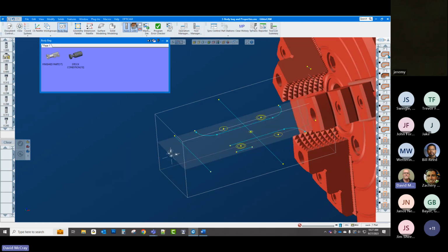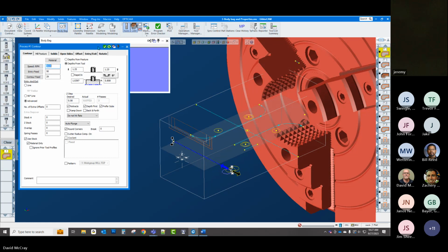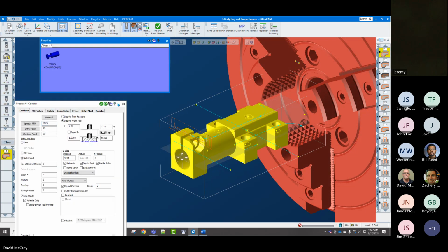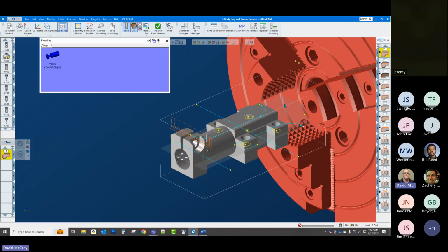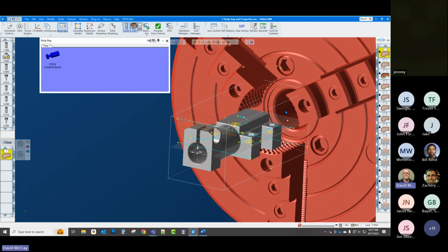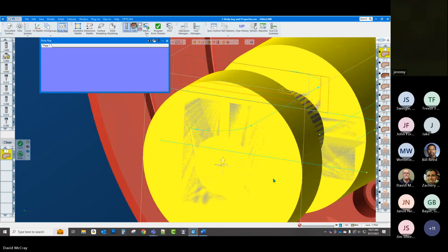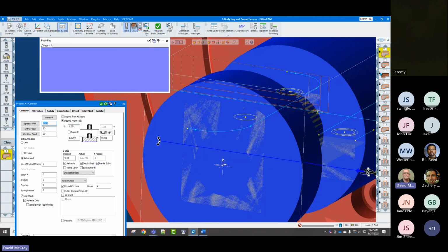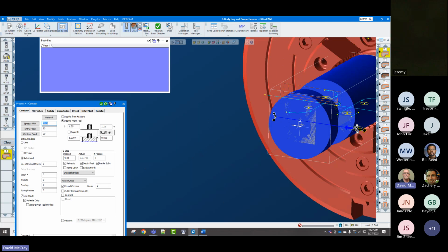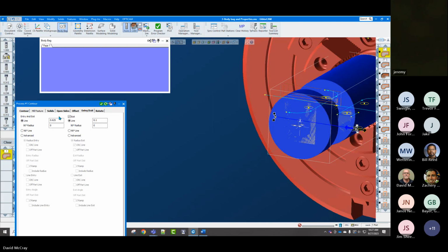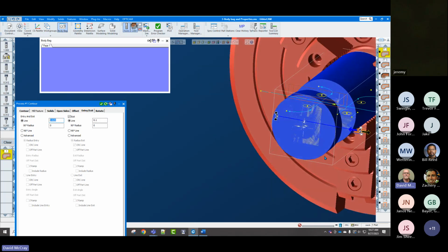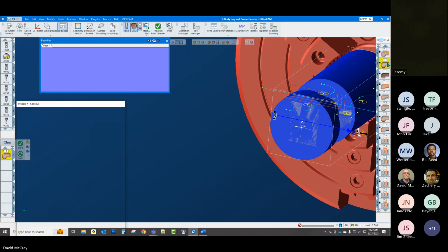So it actually has effect on the toolpath. As I was saying here, I've got a contour op. Let me bring the finished part model back out. And I've got use stock material only. So in the toolpath, you'll notice that if I bring this round out, although my starting marker is out here, my toolpath is actually reading that stock. I've got a 625 entry line on a 1-inch cutter, so a little bit more than half the end mill, and then coming off 100 thou. So it's making the adjustments as necessary just to cut the stock.